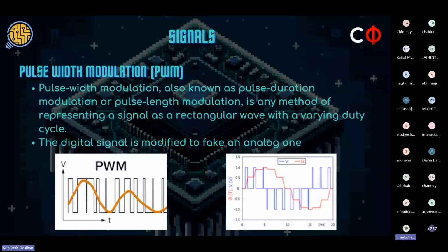Modulation essentially is just encoding information in a signal by varying some properties of the signal. So you can do different things like varying amplitudes, as some of you said, varying frequencies, as some of you said. All this is done to encode some information in a signal, which is generally a periodic signal, so that information can be communicated or transmitted across some medium.